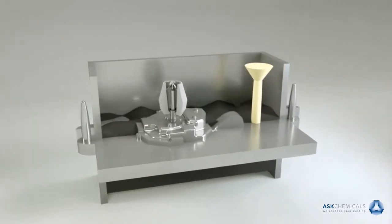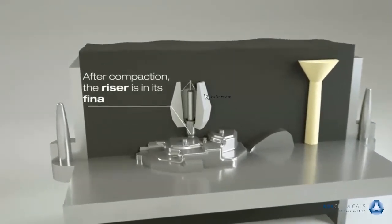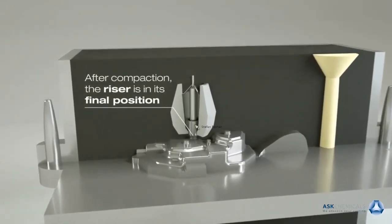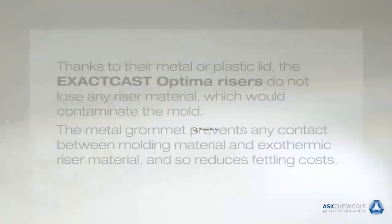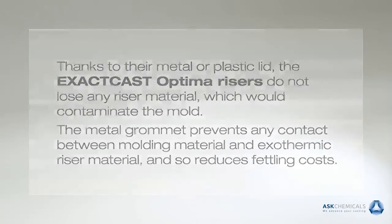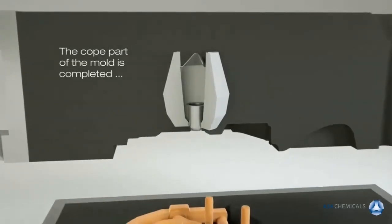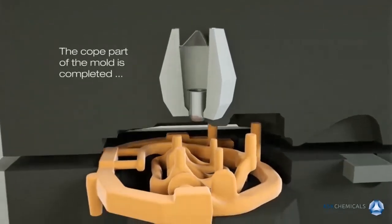The mold is filled with sand and the sand is compacted, and you see that during the compaction the riser is sliding over the metal tube without any forces. With this plastic lid we can also avoid crumbs inside the mold. Now we have the assembling of the mold.